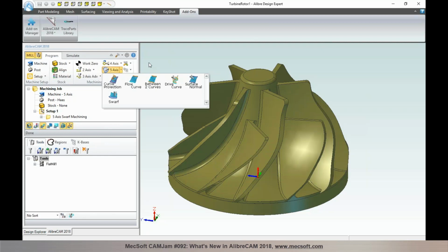We support 3 different classes of 5-axis machine tools. It could be a head-head configuration, where the 2 rotational axes are on the spindle, or it could be a combination of a rotary table and a rotary head, or a table-table configuration, like a trunnion type of machine tool. Some of the Haas machine tools are trunnion type, where you have 2 rotational tables. So you could be programming any of these classes of machine tools, and you can define those in the machine tool setup.